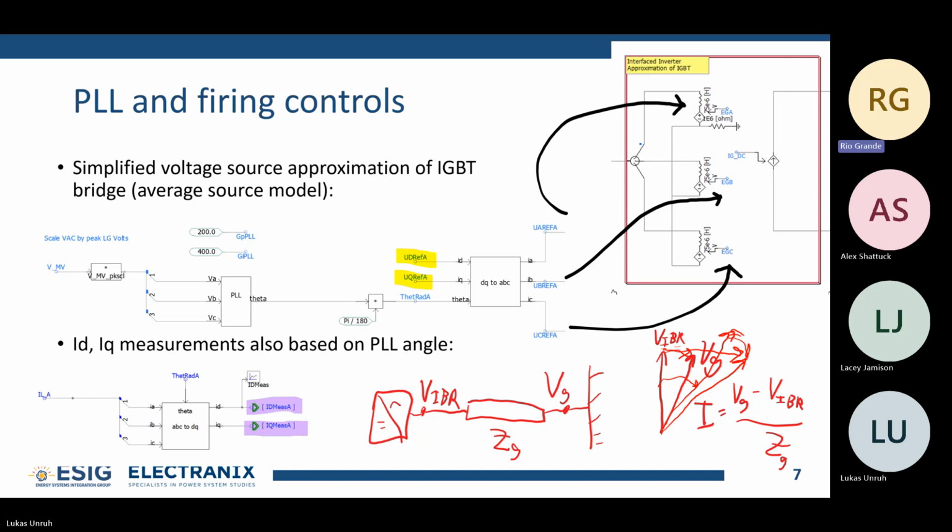You can get an approximation of PLL dynamics, but the PLL looks at instantaneous voltages and tries to track them, and you won't have instantaneous voltages in the phasor domain. So these key dynamics, stabilizing the inverter output for movements in the system, you can only really model in EMT. It's just something to keep in mind.